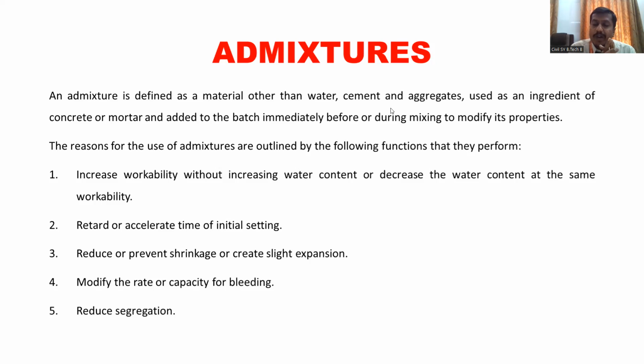Okay, without compromising on the other properties, with the help of admixtures, we can slow down. That is nothing but a retard. We can retard or we can accelerate the initial setting time of the concrete.